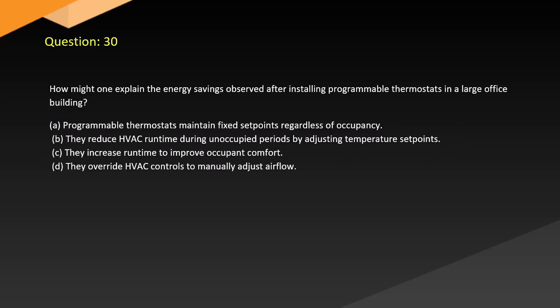Question 30. How might one explain the energy savings observed after installing programmable thermostats in a large office building? A. Programmable thermostats maintain fixed set points regardless of occupancy. B. They reduce HVAC runtime during unoccupied periods by adjusting temperature set points. C. They increase runtime to improve occupant comfort. D. They override HVAC controls to manually adjust airflow.